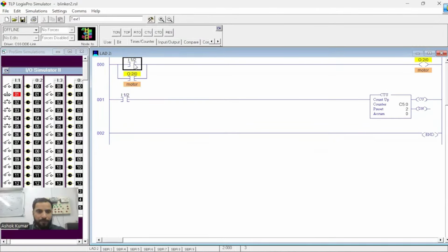When you tap this very first time, output becomes high, correct? Output is held here. That means the logic is started, the motor is started, and at the same time, the counter value is 1. Because you turned on this input once, first time, motor on, and counter value becomes 1. Now, when you turn this input a second time, you want this motor to turn off.